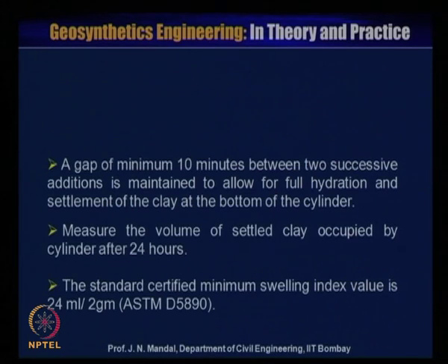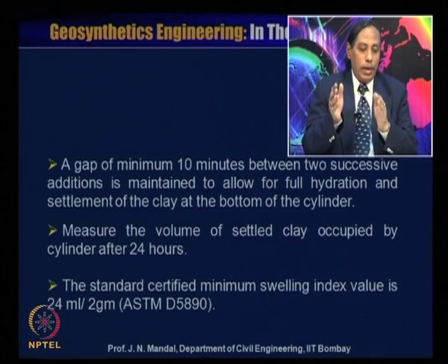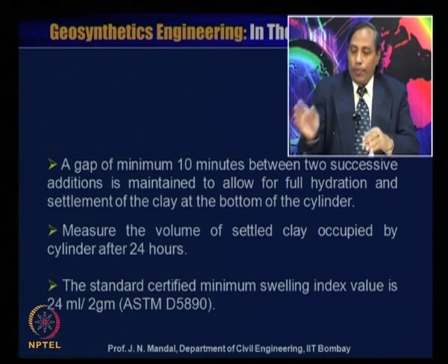If it is not satisfied, you have to be careful to think about what alternative bentonite system is to be added, or whether repetition of the test is needed, but that is the minimum swelling index value needed. Also Heaton etc. also recommended a minimum swelling index of 24 milliliter per 2 gram of bentonite.